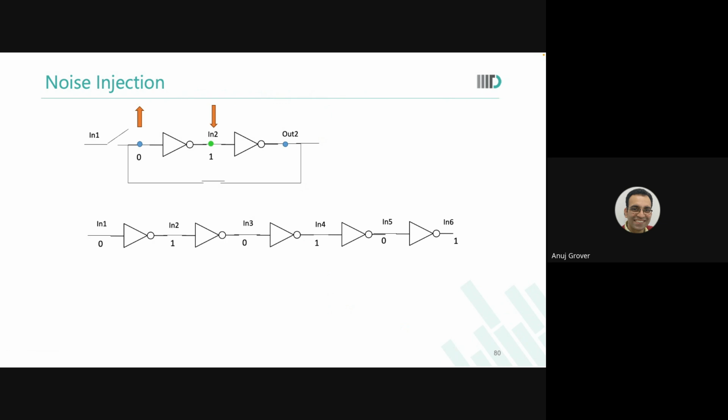So we said that this latch, which is a loop, is actually an infinite loop and therefore an infinite chain of inverters. If I now analyze this infinite chain of inverters, if at the first inverter I had a 0, and at the end I also still have a 0, then it is a safe situation.